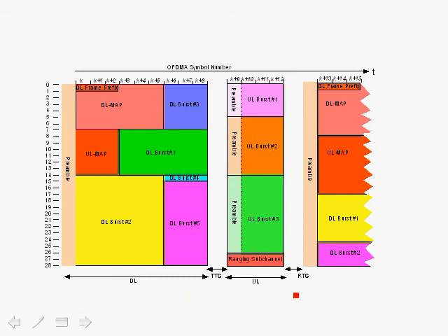However, during the uplink subframe, each subscriber sends its own data burst back to the base station, and therefore it has to allocate its pilots for its data burst, and the location of these pilots changes on a subscriber per subscriber station basis.